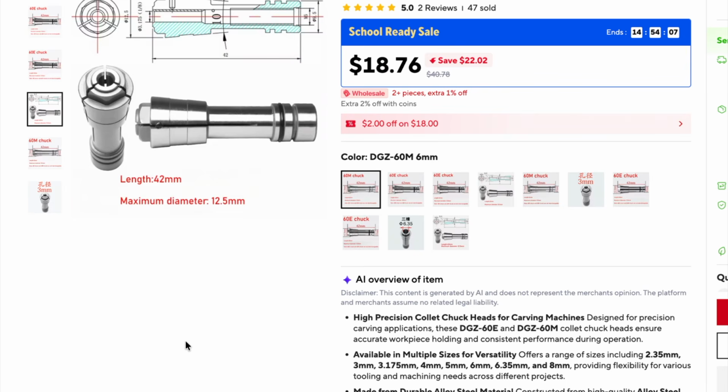So you don't really want to go with standard length tools if you can get away from it. Try to get the shortest tools as possible. So keep that in mind. This is my last recommendation. Also, if you want to get twist drills, you're going to have to keep these really small because just like taps, drills take a lot. You could peck drill, but the machines are not going to have a lot of torque. I would say stay 1/8 inch diameter and under on drills if you want to start holes like that and then helical mill the holes out to finish diameter. It's probably not going to turn a 1/4 inch drill even though it'll fit in the spindle.